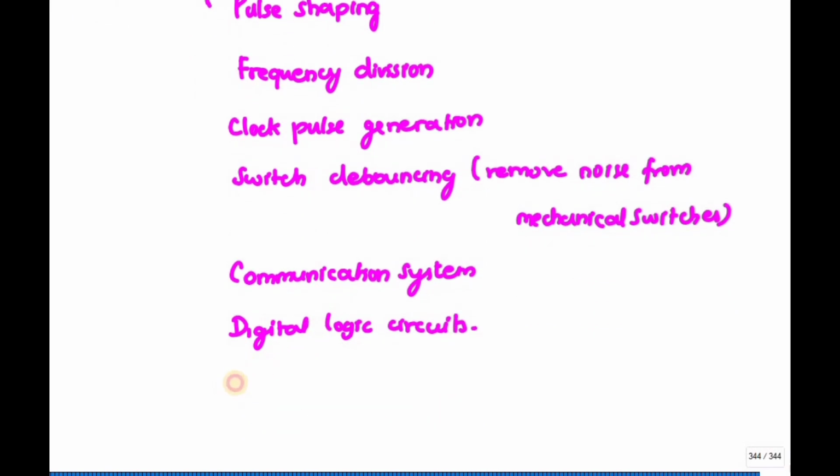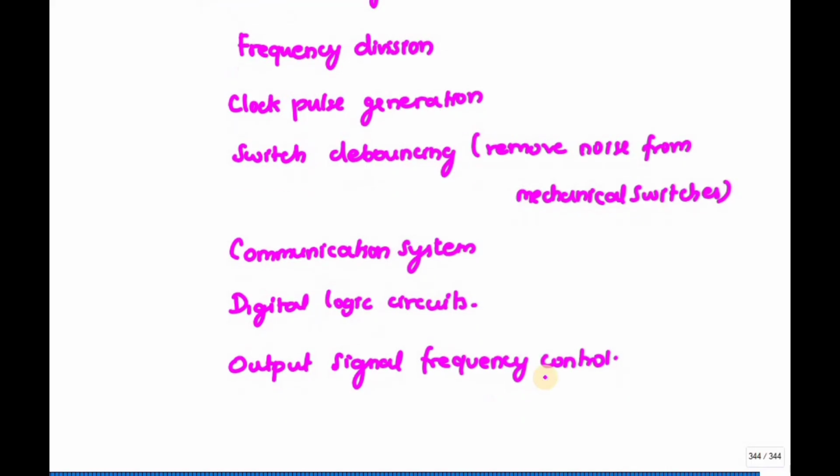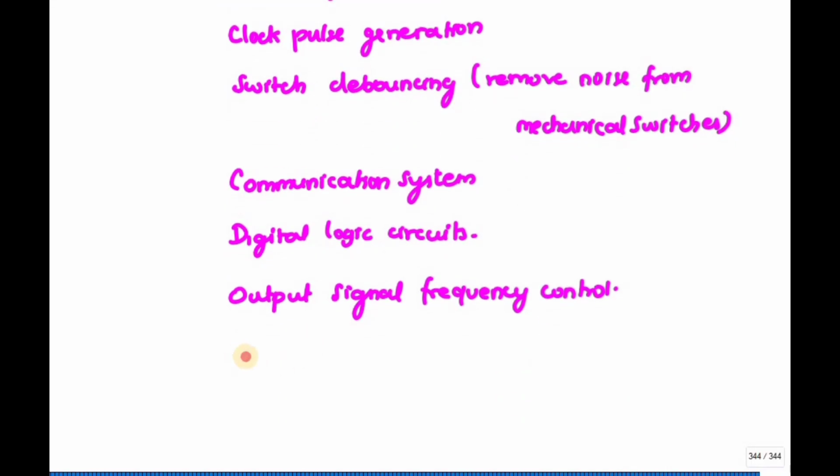So here you can see whenever you have the trigger pulse only, it will go to minus V sat, then it will reach the positive V saturation, right? So whenever there is a trigger pulse only, it will go to minus V saturation. Otherwise, it will remain in the V saturation state only.